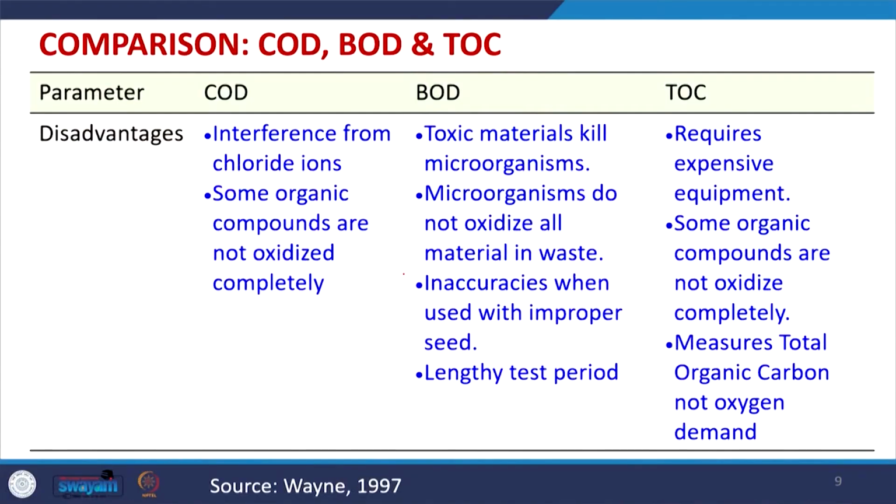Also, it is a lengthy test period, and during the preparation of sample bottles, a lot of precautions have to be taken so that there are no oxygen bubbles etc. inside the water bottle. Otherwise, the BOD test fails after 3 days or 5 days. Then we feel that this is very bad and we have to do it again. So, a lot of expertise is required for actually performing the BOD test. For TOC, the disadvantage is that we require a very good TOC analyzer, and that will be very costly.